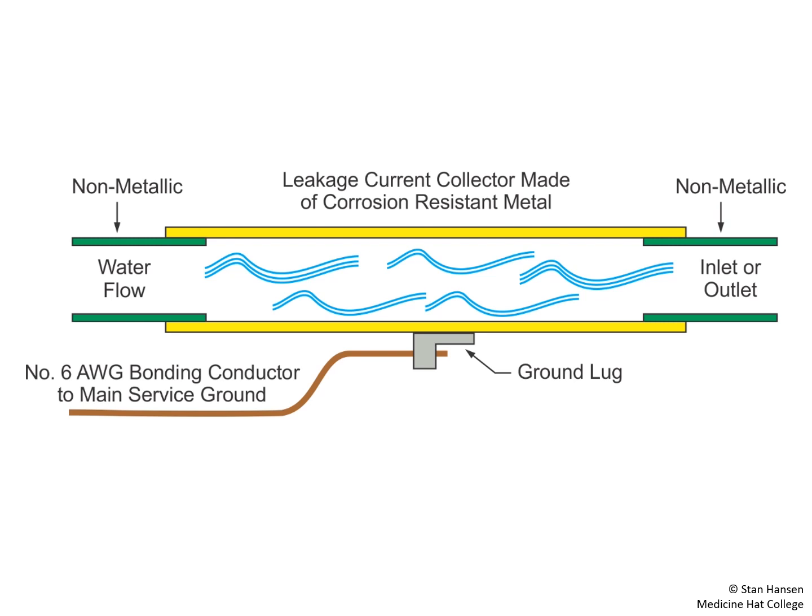If we're dealing with any field assembled units, we can only use the approved parts, and they must be installed according to other rules within this section. If we're dealing with air blowers, they're not meant to get wet, so they need to be protected from the water contact. And we do this either by locating it in a place where it won't get wet, or some other means such as guarding. Make sure you're looking through Appendix B on 68-406 for other information with this rule.